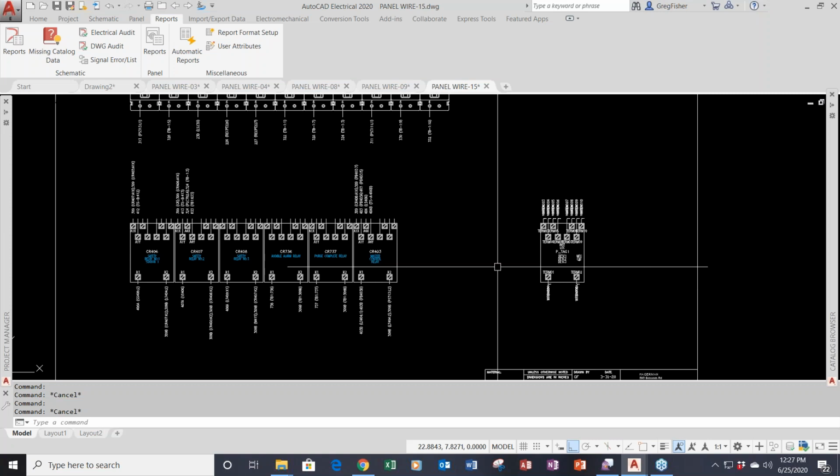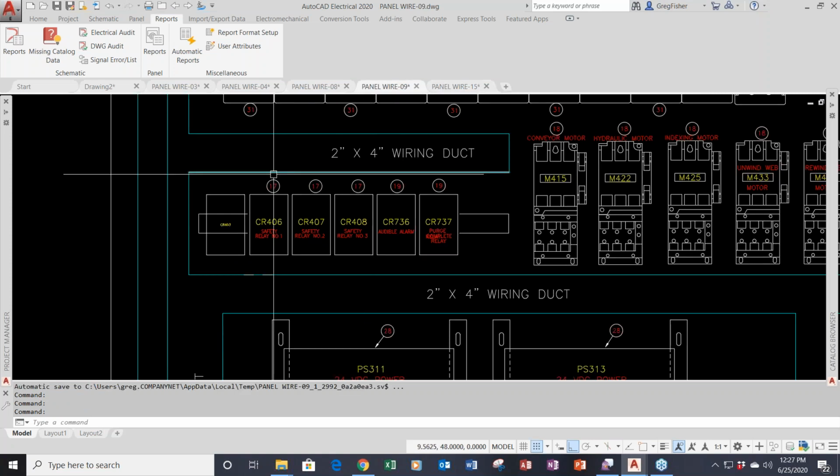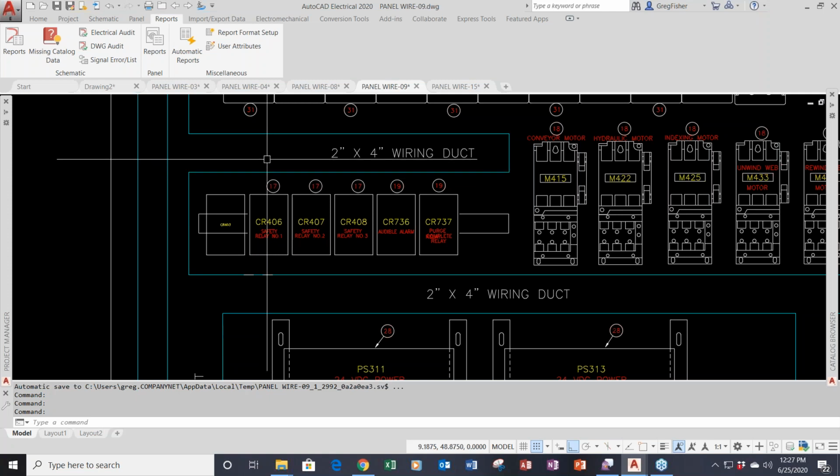Or, like I said as well, I've seen other people include the attributes in their standard footprint symbol, and you get into a layering organization. You could take all those attributes that I had on the footprint symbols and add them to your master footprint symbol, and you didn't want to create a second one, you could add the wiring information to your original ones.